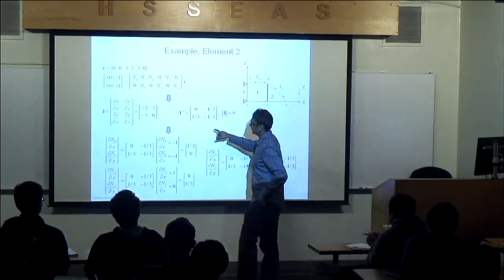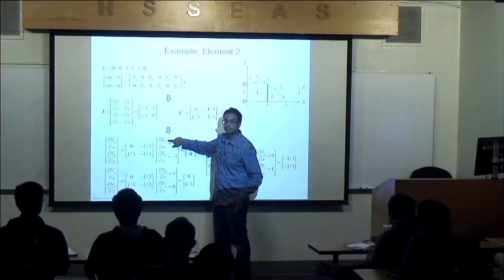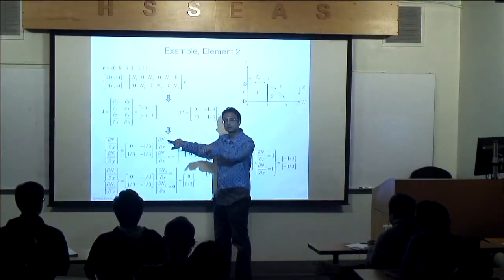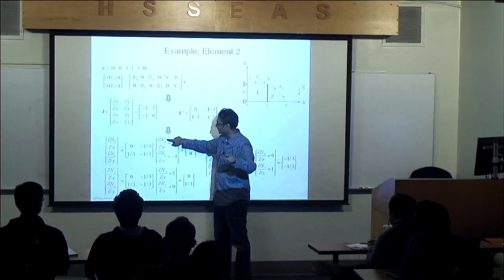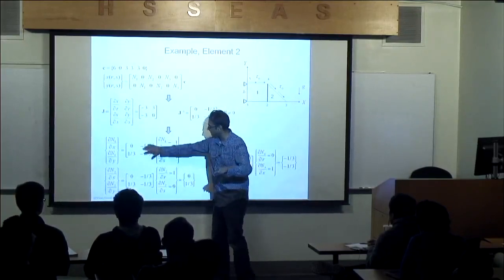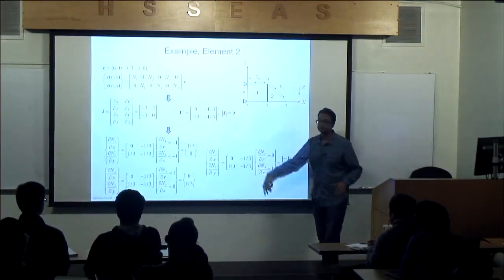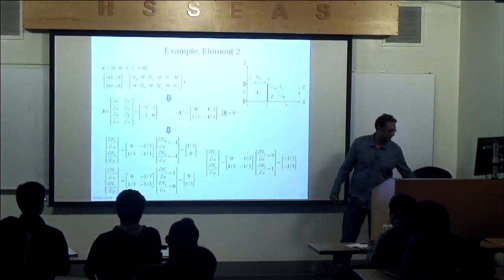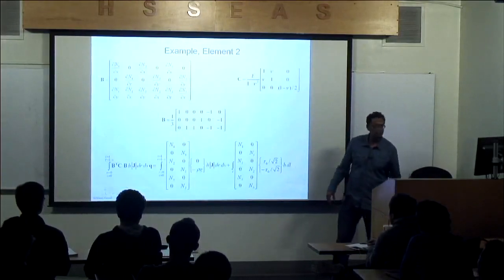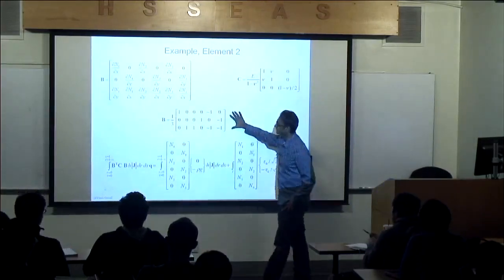Then, once I have the Jacobian, I can also find the derivatives. If you remember from the previous lecture, shape function 1 was 1 minus r minus s, remember? So the derivative of that with respect to r is minus 1. And then you can calculate the derivatives, multiply all this, and you get very nice numbers, actually. They're all numbers. I can plug this into B bold, and when I do that, I get a matrix of numbers.